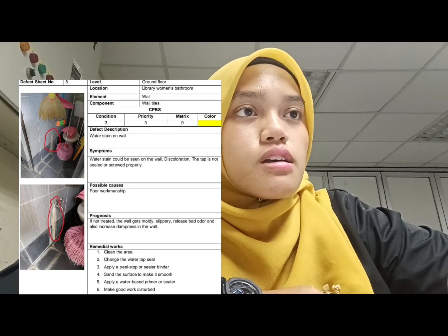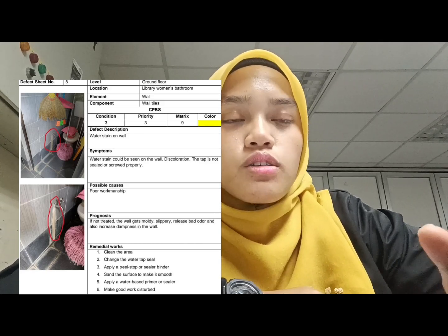discoloration, the tap is not sealed or screwed properly, and the possible causes is poor workmanship as well. And the prognosis is if it's not treated, the wall will get moldy, slippery, and also will release bad odor and also increase dampness in the walls.